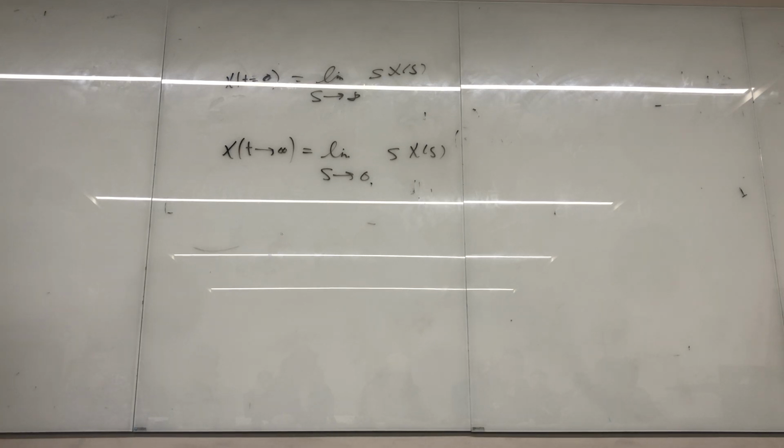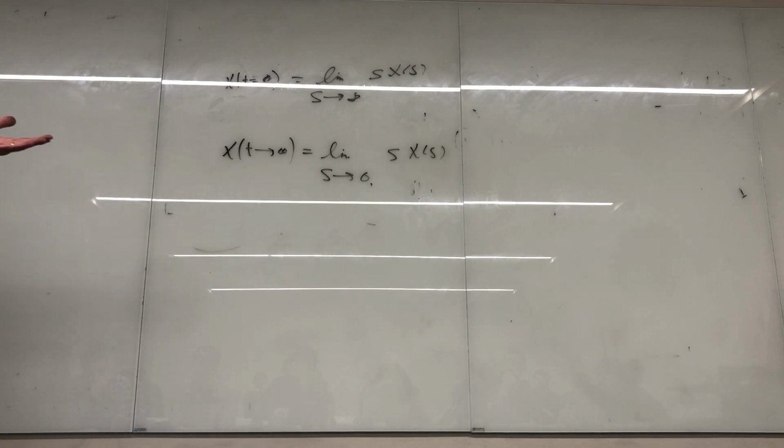Just think of this. If you had a current source and you put a capacitor across it, and the current source was constant with time, what happens to the voltage across that capacitor? It goes to infinity, right? And what does that mean in the practical sense? It's going to short out through the dielectric and destroy the capacitor eventually. It's destructive. That's an unstable system, as simple as I can put it.